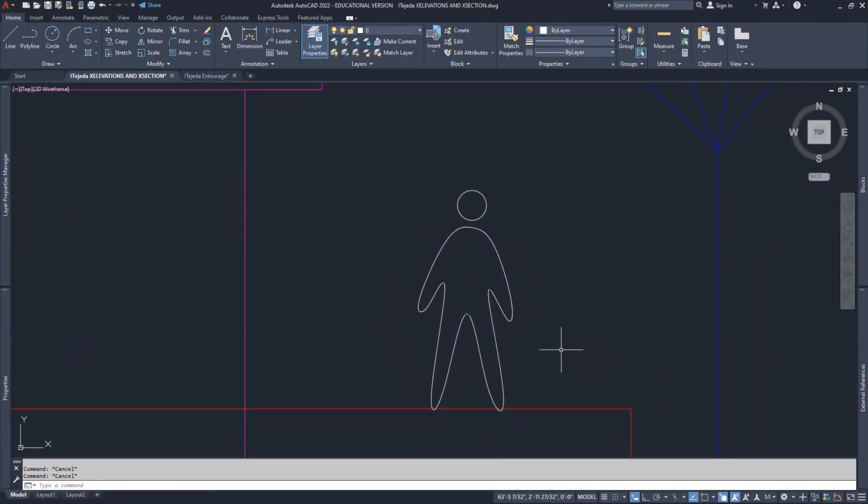Another way that we have drawn figures as well is to, let's see, I'll make a copy of that head and I'll bring it over here. I'll keep it at the same height for now. Bring it over there, tap my escape key, and then I'll simply draw a line. I'll take it across, about the width of what I believe to be a figure like that. I will turn off my ortho. I'll bring it over here, more or less to the center. In fact, I'll try to track that midpoint.